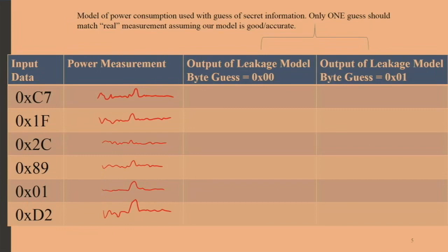To exploit power analysis, there's a bunch of ways to do it. Most of them have this idea of some sort of fundamental model: there's secret data inside the chip I need to get out of the chip. And I'm going to make some assumptions regarding what the power measurement looks like when some secret key byte is some value. We could do that with a template. We could record a whole bunch of data being processed with different encryption keys and figure out exactly what it might look like for every encryption key, every part of the encryption key. Or we can use the easier way. We use some really basic models that have really fundamental underlying assumptions.